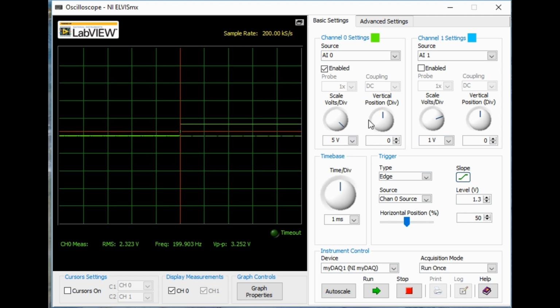There it is there. We don't have the resolution, unfortunately, to look at any type of ringing that we may be getting on there. It just appears as a solid straight line, so you miss all of the information you would need there, because of course if I'm going to be driving this with a Tesla coil, I will want to be limiting the amount of current available to the gate so that I don't burn out the IR2110. You can draw a couple of amps from this very quickly. You can damage it. So if you put a gate resistor in there, usually about 5 ohms or something like that, that can help, and it would smooth this curve out a bit, so it wouldn't be such a solid thing like this, and it would usually have some ringing on the top like that.